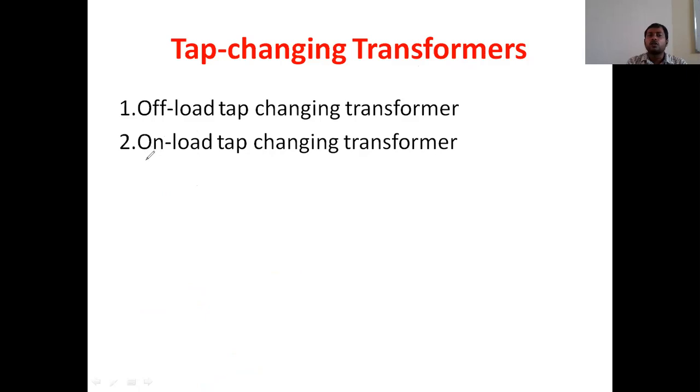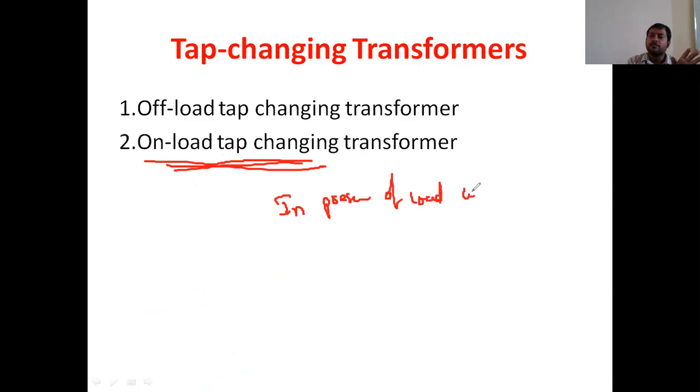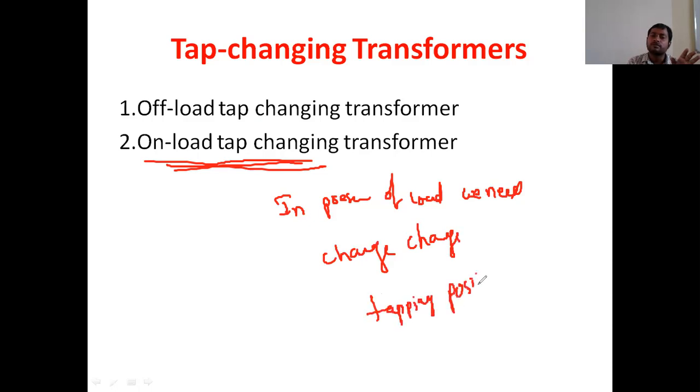The next one is on-load tap changing of the transformer. On-load tap changing is nothing but in the presence of load. In the presence of load, we need to change the tapping position without interrupting the load.